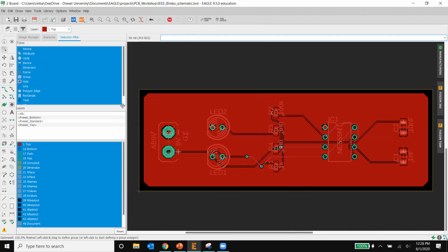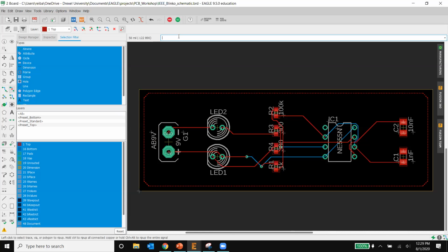So let me remove the polygon again, and we remove the polygon by doing ratsnest and then we go to ripup all visible polygons. And actually, an advice here that you could probably use after you do that, so what happened now won't happen again, you probably can just do set poly off, right?